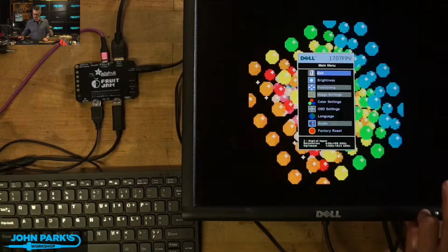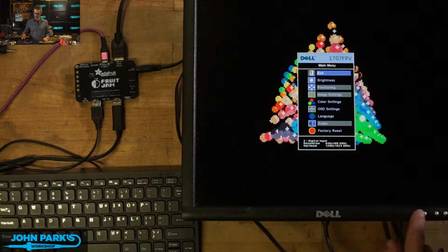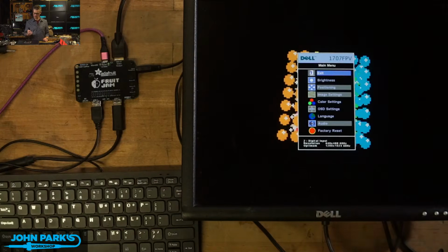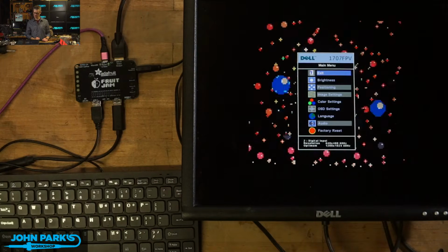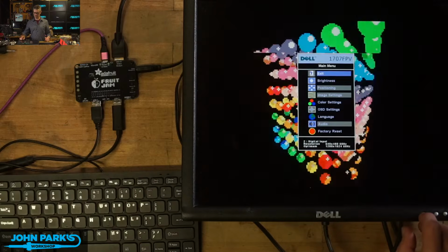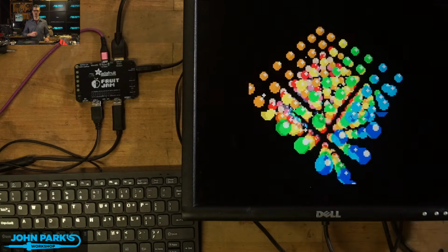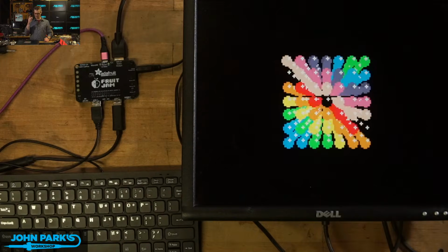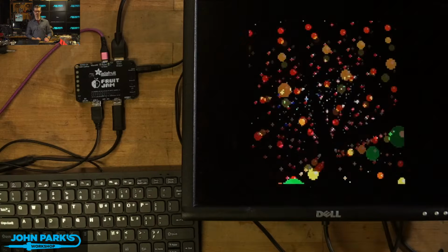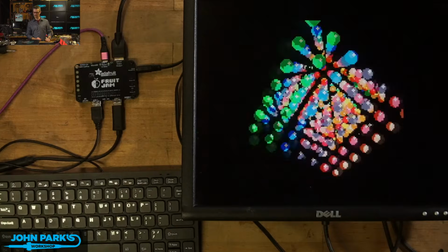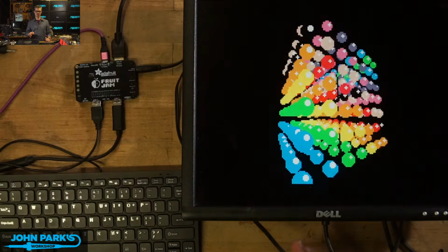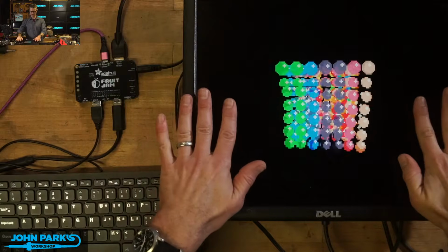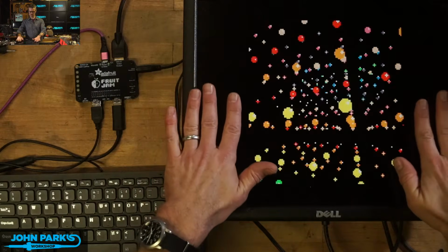And if I go to this monitor's menu, you'll see down here it says digital input 2 is what's being used. Resolution is 640 by 480 at 60 hertz, which is great because that's almost the most standard video format you're going to find on monitors. So even though this has a DVI monitor input, or if you have a TV with an HDMI input, very likely is going to accept happily that 640 by 480, and you can see it's letterboxed. So are pillar boxed. So we have actually both.